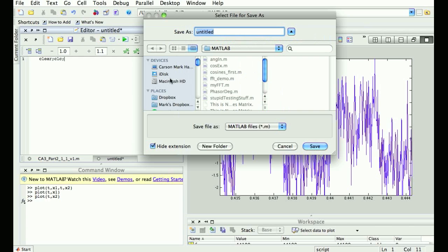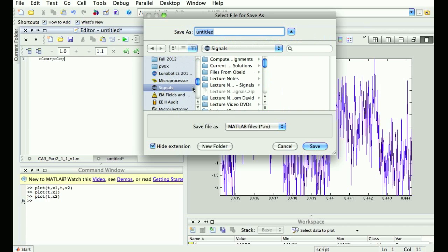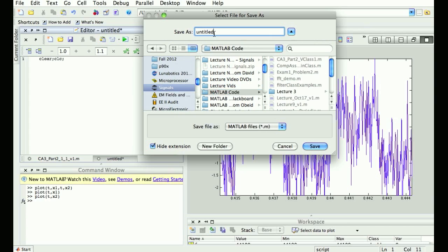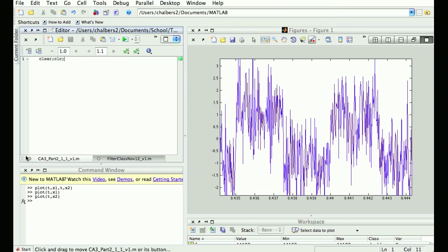Yes, sir. Yeah, I picked something in the passband because I wanted to make sure that I evaluated what the gain was in the passband. Well, the 100 and the 10,000 are at the cutoff frequency, so they're not a good representative of what's going on in the passband. But in theory, putting any number in the passband would have worked.